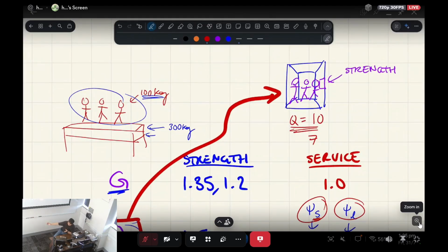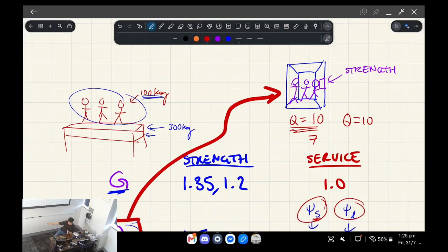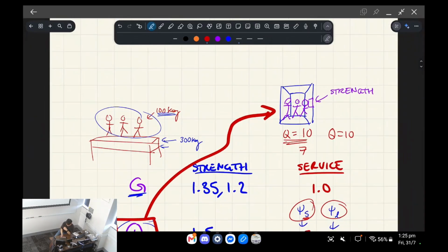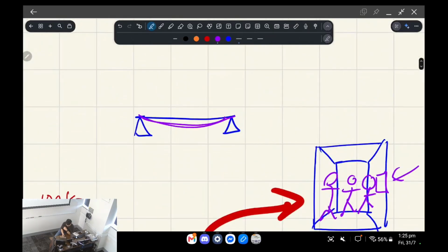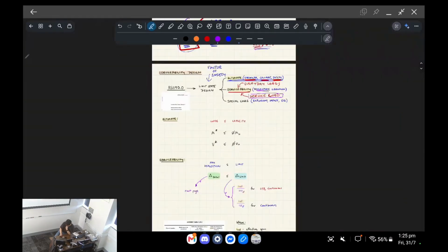In the long term, it's saying, over a long stretch of time, what's the average loading? So for example, if we're accounting for 10 people, because UNSW is a school, and there are holiday periods, over a long stretch of time there could be long stretches where no one's using the elevator. And so when we're thinking of this in the context of deflection for a beam, it gives the beam a little bit of time to restore the sagging. So that's long term.